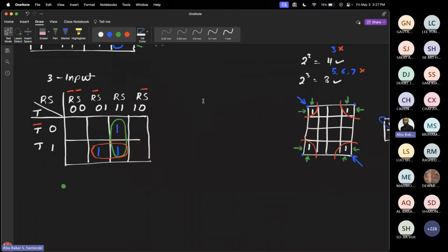So that means for the green group, where we have these two members, this guy and this guy, we're going to group them with AND. So we're going to say R. You can see there's an R here. Then there's an S. And then there's a T bar. So that's the first one. We will continue. The second one is also another R and another S and T. So this is the green group. These two ones, their values for R, S and T are as follows, and we've connected them with an AND gate.